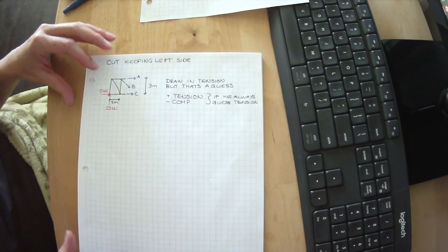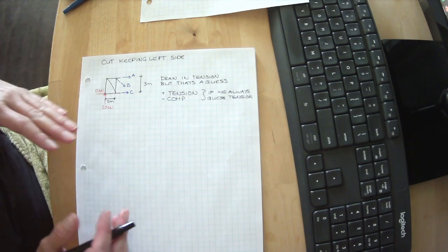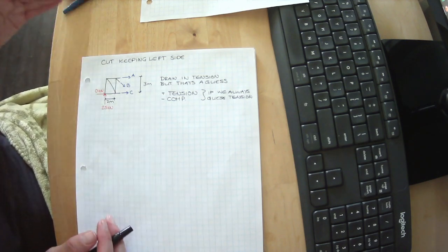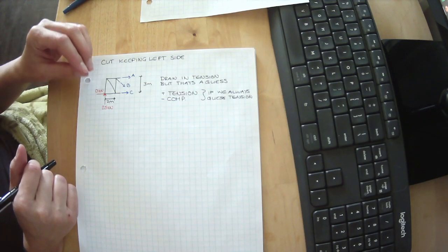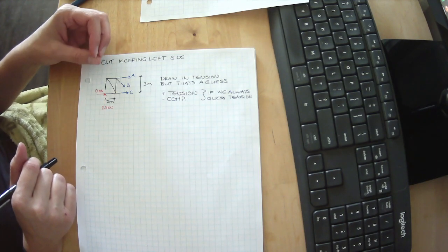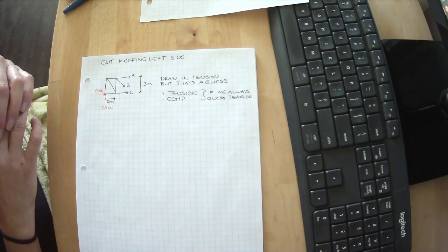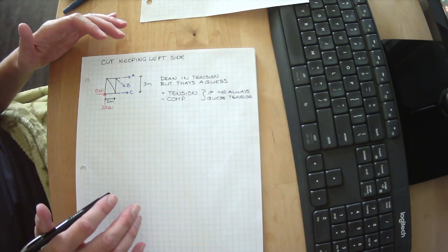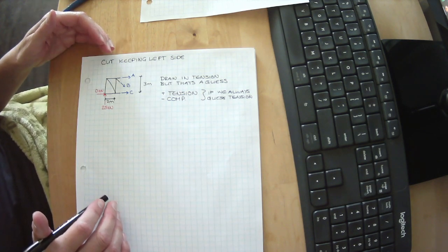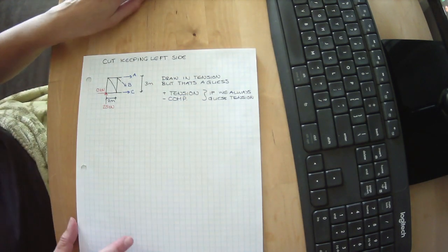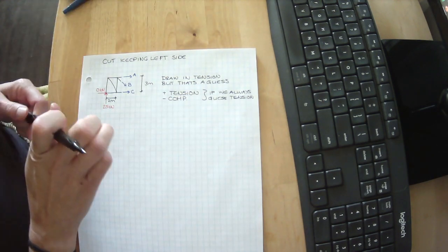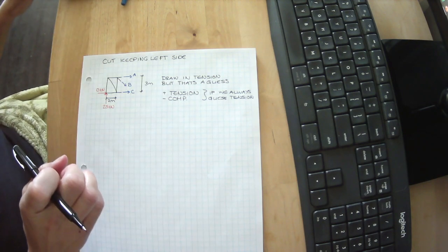That can start to be a real pain in the butt because then you have to always go back and check, did I guess tension or compression? So I'm giving you an easy trick to always know quickly if your element is in tension or compression. Always guess tension. And so if you're wrong and get a negative answer, you will know that always means it's actually in compression. So let's start solving this one for that.